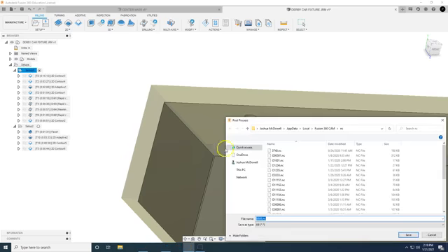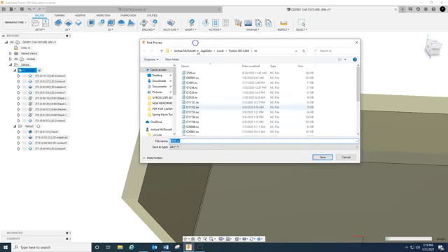All right, so I probably got a little bit ahead of myself. I clicked post back there. Once you get all that stuff set, then you click post. If you notice, it's trying to output it as a .nc file, which is fine. This is where I always put the O in. So the letter O, not 0, the letter O. And then I simply save.